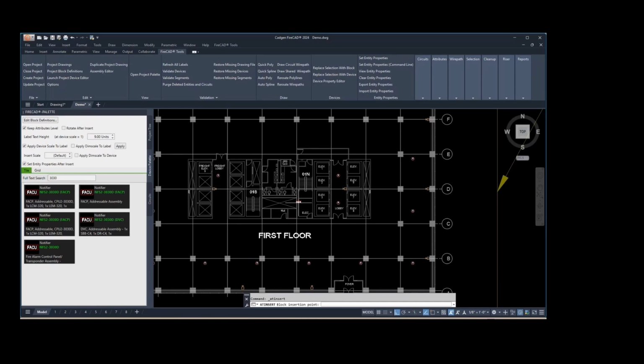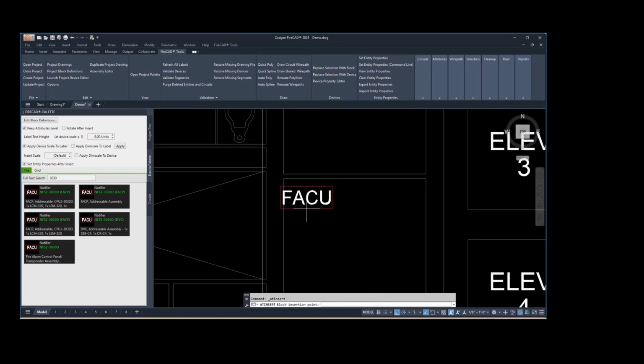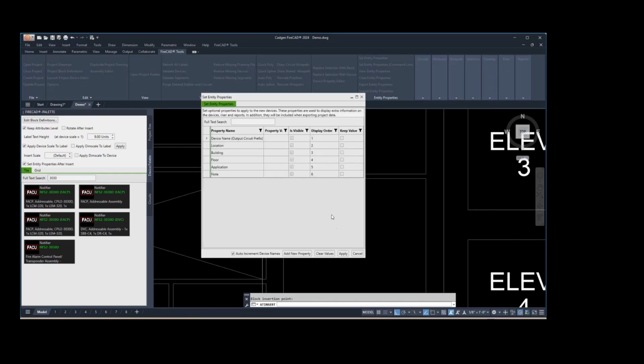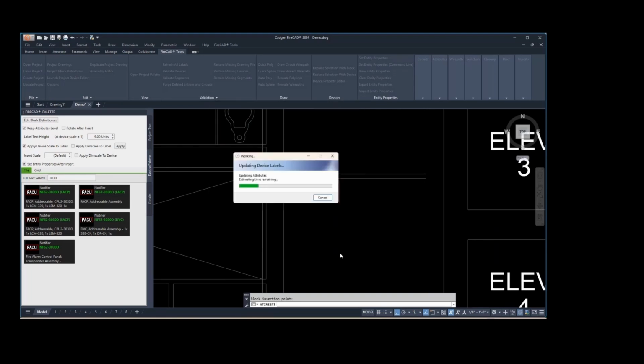And we will put that right here in this electrical room by left clicking, and then we right click, and it asks us if we want to give it a name. You don't have to, it's optional, but I'm going to give it a name, and it's going to be called P1, which is, in my language, panel number 1.